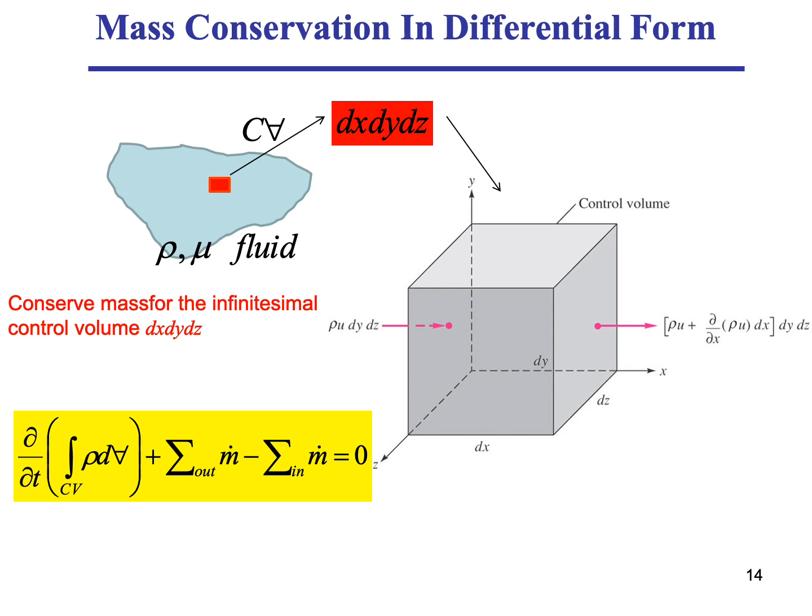So you want to remember that this control volume is fixed in place. This is what we call an Eulerian frame of reference. You will see a video link on Moodle that explains the difference between an Eulerian and a Lagrangian frame of reference. Our study in chapter 4 is concerned with an Eulerian frame of reference. So if you encounter the Lagrangian frame of reference, as you will see in the video, that's not what we're talking about.